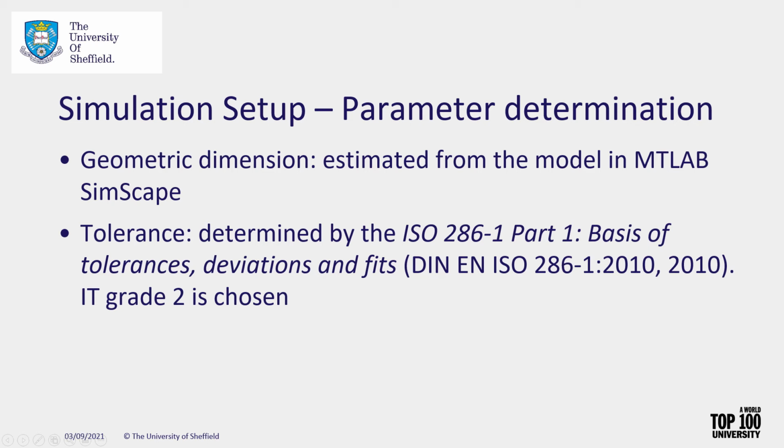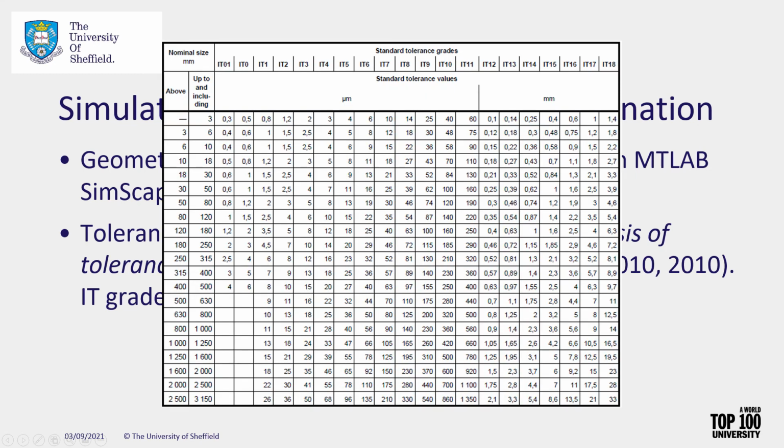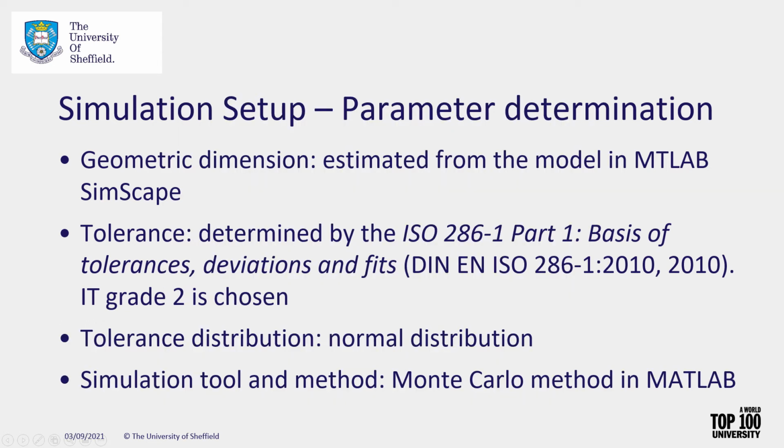The tolerance for each part is determined by the ISO standard, ISO 286-1. Here is the IT grade table. In this project, IT grade 2 is chosen. The simulation is implemented by Monte Carlo simulation in MATLAB, and the tolerance distribution is normal distribution.